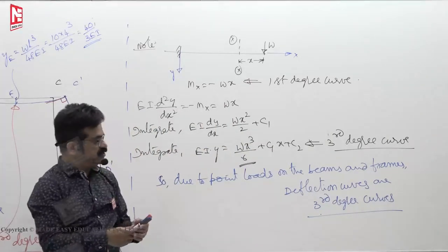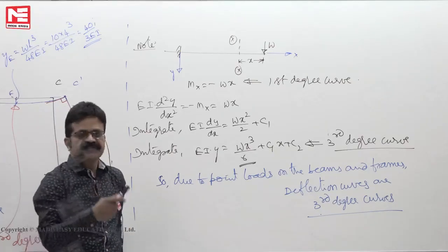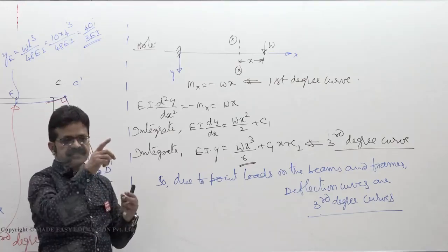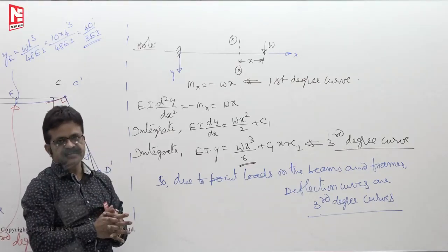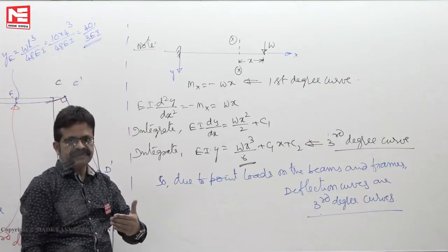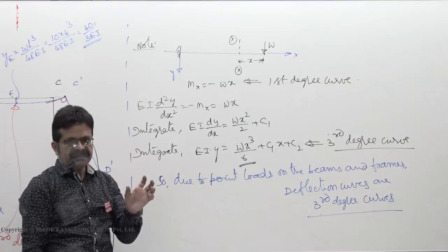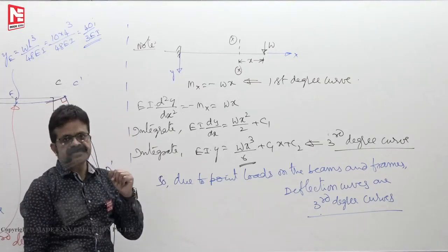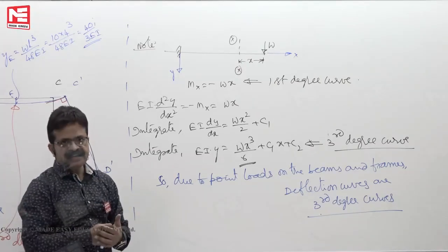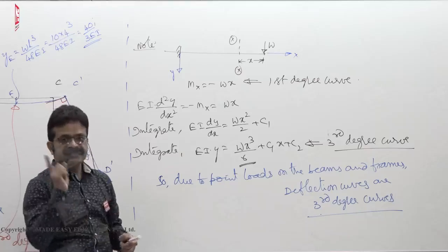In the arches, the influence line diagram itself for horizontal thrust, etc., is a fourth degree curve, because for the indeterminate structures, when you take the integral of M x squared dx by the integral of y squared dx and simplify, the horizontal thrust has x to the power 4 terms. Determinate structures anyhow give straight lines, while indeterminate structures give a fourth degree curve. That is for the stress functions.